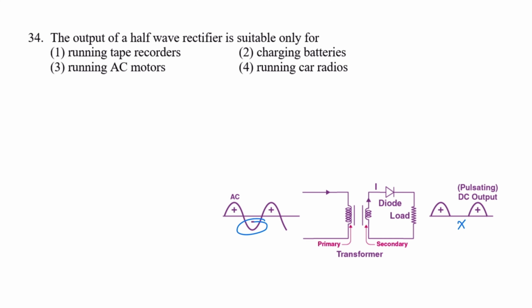This half wave rectifier is rarely used in practice and is never preferred as power supply of an audio circuit because of high ripple factor. As ripple factor is high, hence it is never used in practice as a power supply. High ripple factor will result in noise at the input of audio signal which will affect the audio quality. Next point. The DC output power available from a half wave rectifier is not satisfactory to make a general power supply. Hence, it is used in some applications like battery charging.